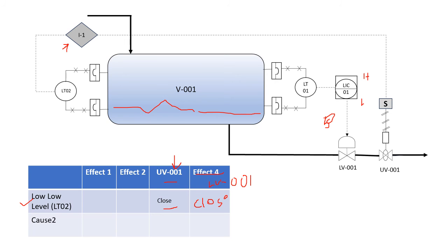So in this case, what happens? Our control valve gets associated with a solenoid, right? This is an additional thing. Sometimes that is put in with the LV, but that is not a very good design, because then the segregation of the control layer and the protection layer is getting mixed, which is not a good design. But still, there is a chance of this.